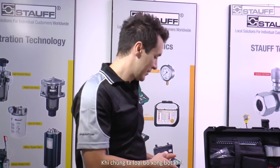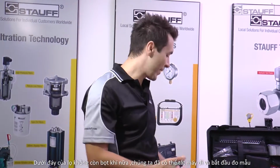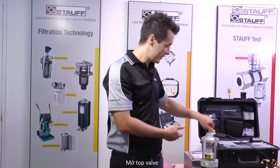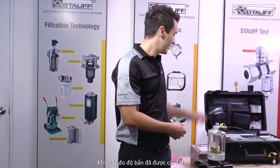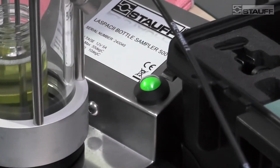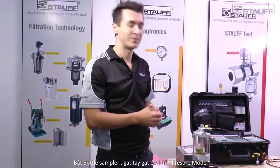Once we finish removing all the air bubbles, so there's no more bubbles down the bottom, now we are ready to turn it off and then commence the test. So we turn the bottle sampler off, open up the top valve, change the handle to pressure mode. When the machine's already set, so make sure the machine's turned on, and then start the bottle sampler in the pressure mode.